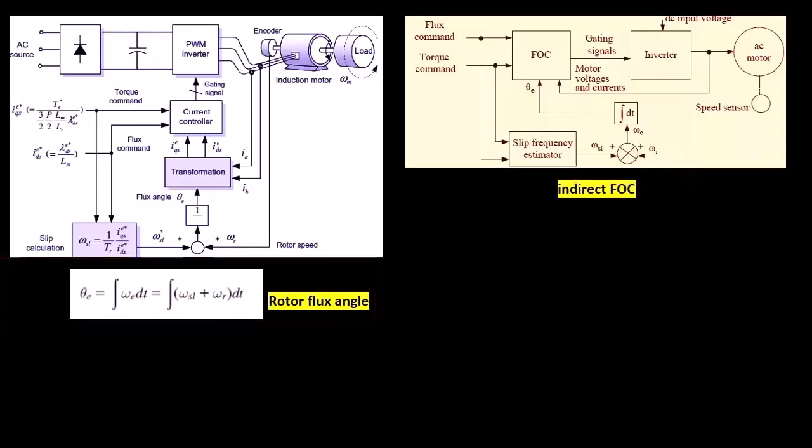Sensorless control is a collective term for field-oriented control methods that do not utilize speed or position sensors. The vector control without a speed sensor is attractive in practical applications, since it eliminates many problems in sensor installation, cabling, processing circuit, and low signal-to-noise ratio. Enhancing the torque and speed performance in the low-speed region is an ongoing problem in sensorless control.